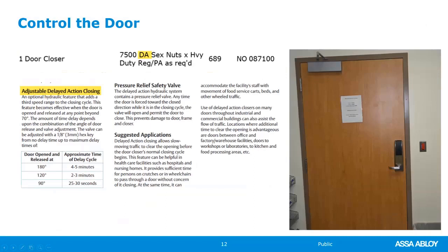The rule of thumb and what DHI has always taught is each piece of hardware does its own separate job. An overhead stop has a bigger spring and it spreads out and disperses the force when that door hits the cushioning spring. It spreads it out over a much bigger area along the width of the door than the little parallel arm shoe would.